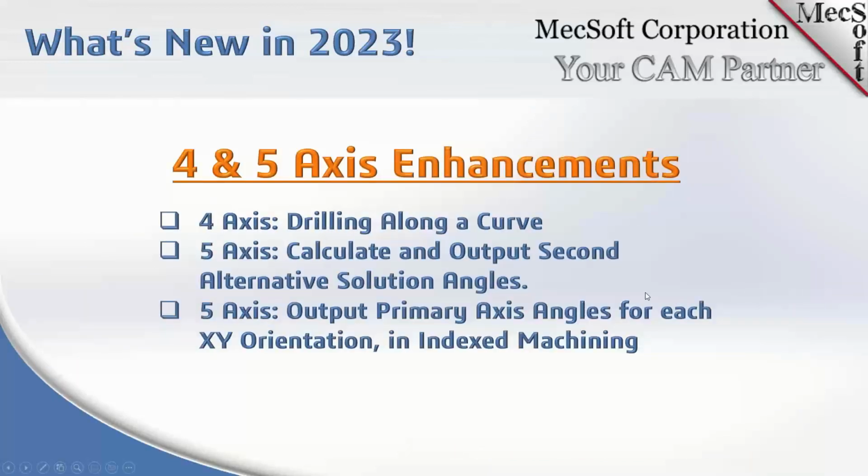Now the 4 and 5-axis enhancements, we already mentioned the 4-axis drilling along a curve. We also enhanced 5-axis index output, how we handle and output the rotation angles in 5-axis. So now we handle the output of the second alternative solution angles, and then also in 5-axis when you're reorienting the Z-axis. We'll show you that as well.